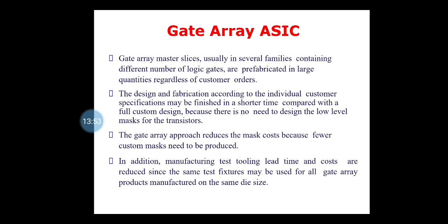The gate array master slices, usually in several families containing different numbers of logic gates, are prefabricated in large quantities regardless of customers' orders. The design and the fabrication according to the individual customer specifications may be finished in shorter time compared with a full custom design because there is no need to design the low level masks for the transistors.